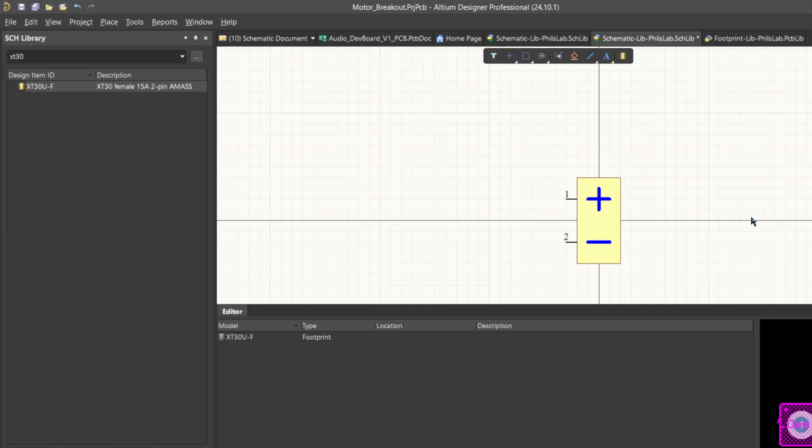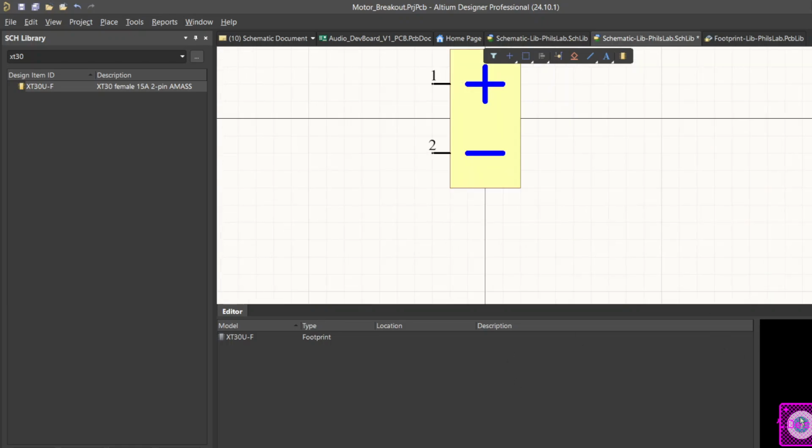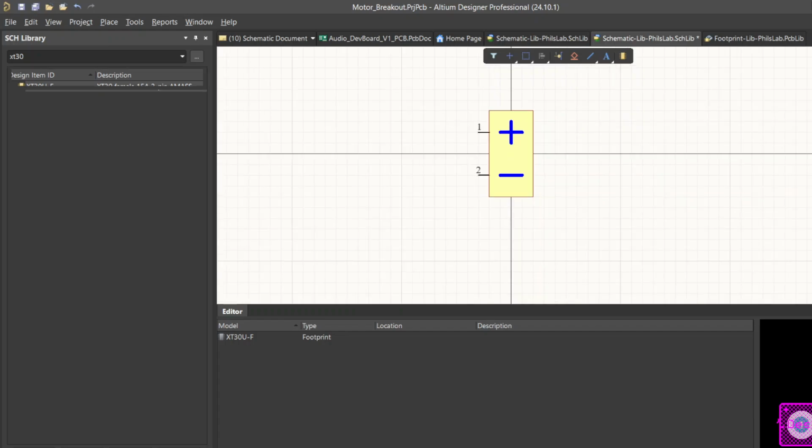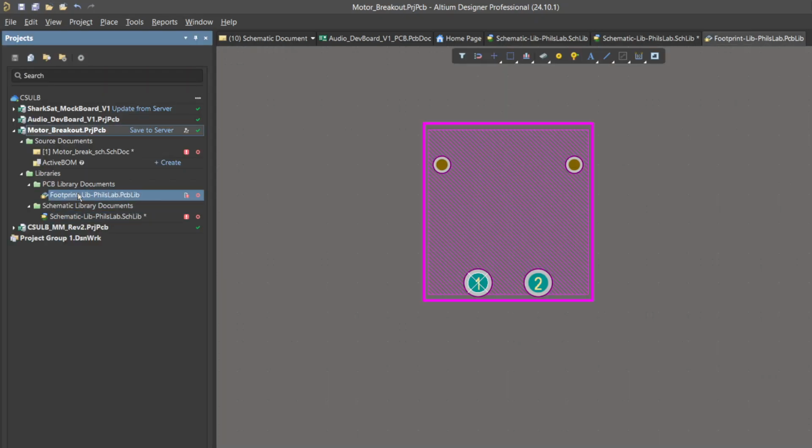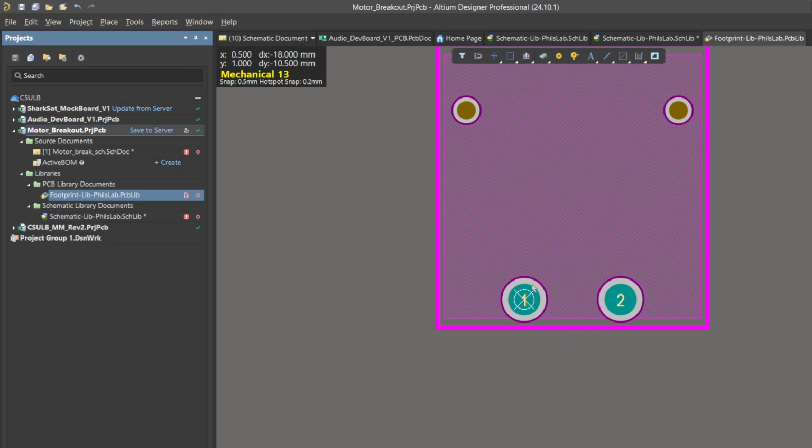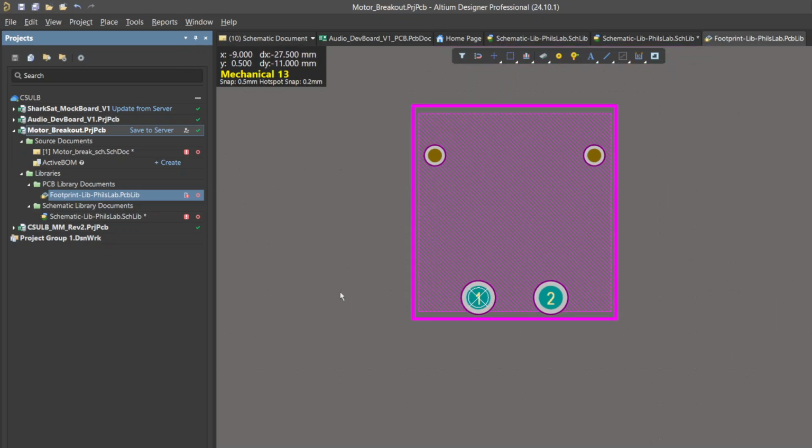One more thing I want to double check before we move forward. You'll notice in this one, the positive is pin number 1 and the negative is pin number 2. You can notice that there's a slant on the negative. I want to confirm that the one we just did is correct for this being positive and this being negative.